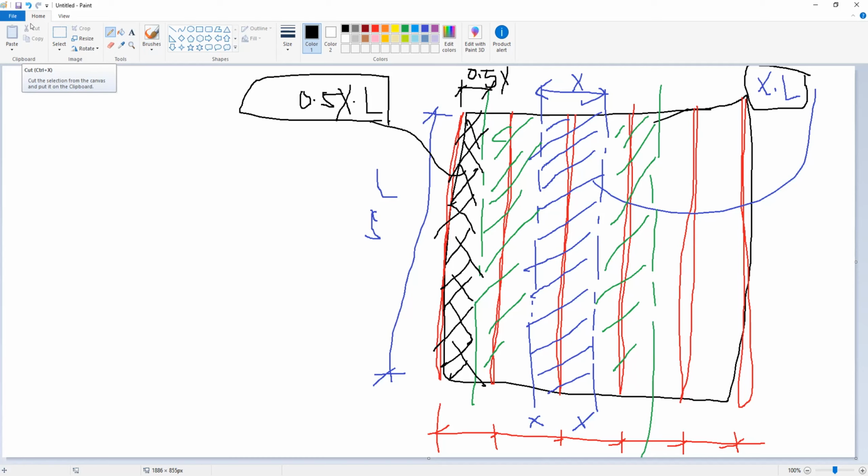Yeah, because I'm thinking, because it has less area, it should be the reverse. It should be more. It can actually carry a little bit more, if I'm using the same purlin size. Anyway, for the edge spacing, maybe it will also get something from the girts or other elements supported by the purlin, because at the top of the wall the girts may transfer some load to the purlins.